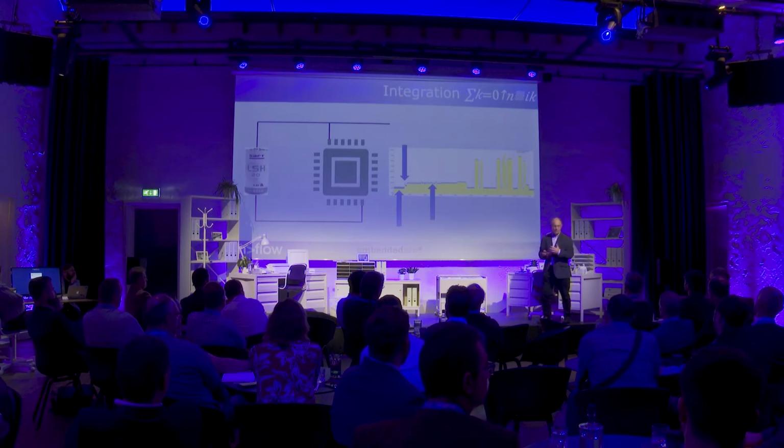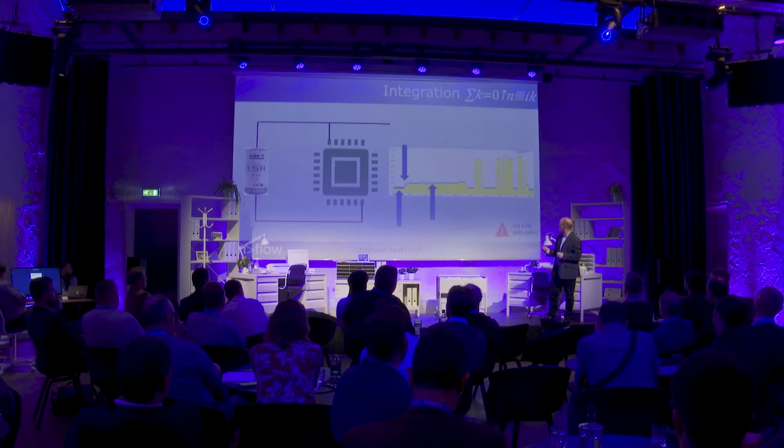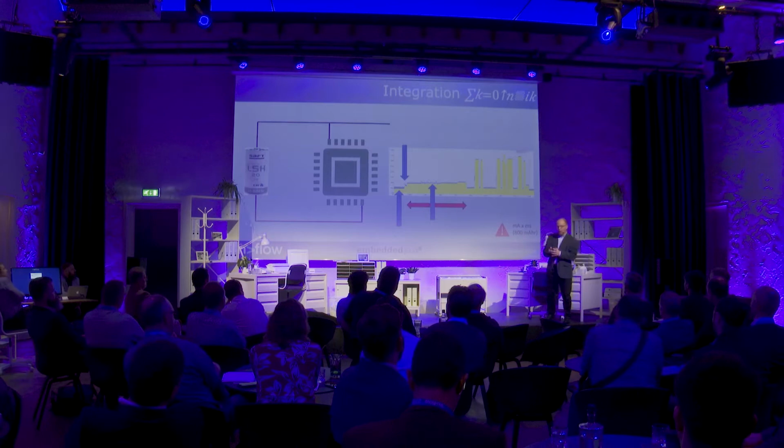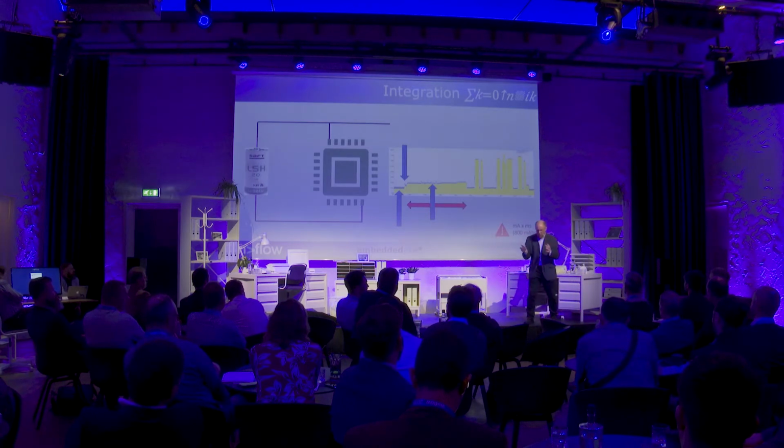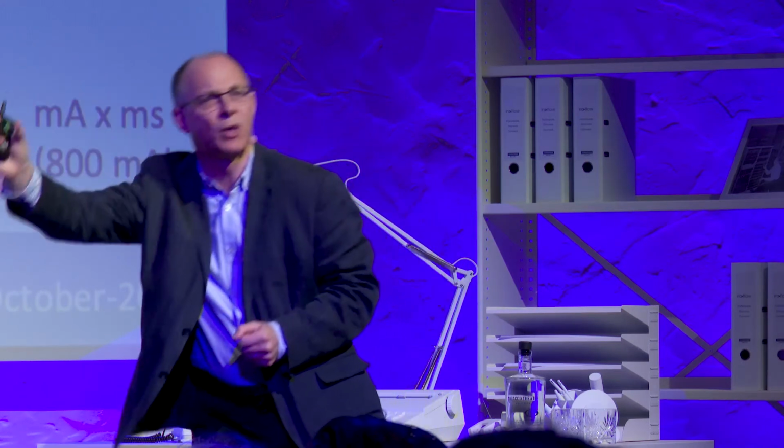But it's not very clear in the datasheet what those numbers actually mean and in what use cases they've been done. And of course, the other thing that we need to know is how long is the microcontroller going to be in these different modes? Well, I know that my node's going to wake up every 15 minutes. So that's 15 minutes in the stop mode. But how long will it take to wake up? How long will it take to work out what the sensor's doing? How long will it take to send the packet off to the cloud? So these things are quite complicated.